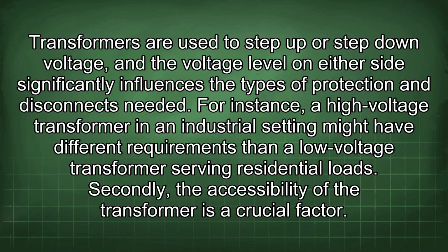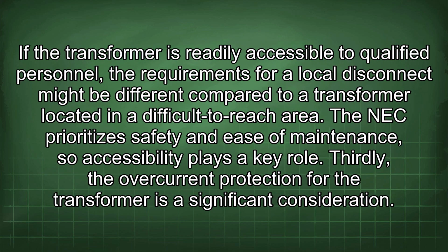Secondly, the accessibility of the transformer is a crucial factor. If the transformer is readily accessible to qualified personnel, the requirements for a local disconnect might be different compared to a transformer located in a difficult-to-reach area. The NEC prioritizes safety and ease of maintenance, so accessibility plays a key role.